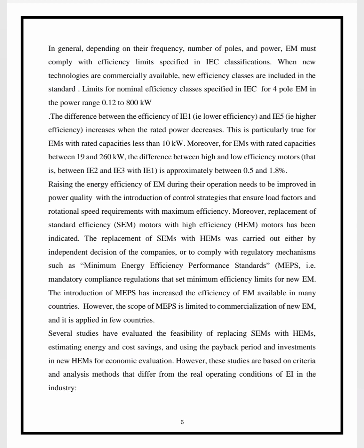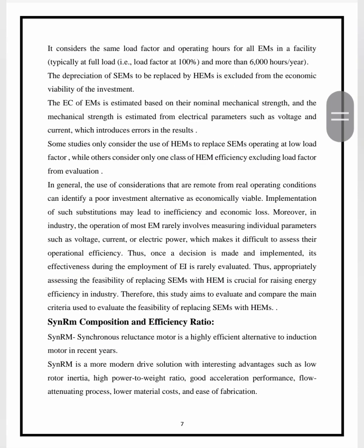Several studies have evaluated the feasibility of replacing standard efficiency motors with high efficiency motors, estimating energy and cost savings and using the payback periods and investments in new high efficiency motors for economic evaluation. However, these studies are based on criteria and analysis methods that differ from the real operating conditions of electric motors. It considers the same load factor and operating hours for the motors in the facility, typically a full load, for example, load factor at 100% and more than 6,000 hours per year.